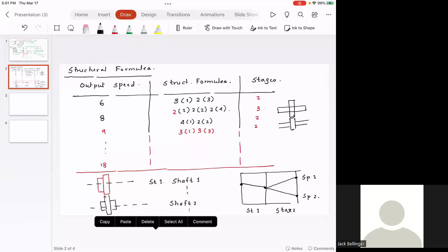And what you can do is you can have another gear attaching or connecting to the gear that is offsetted. So now you can engage this first pair and achieve the reduction ratio 1. You can engage the second pair. So basically this gear, this shaft, the whole thing gets shifted.